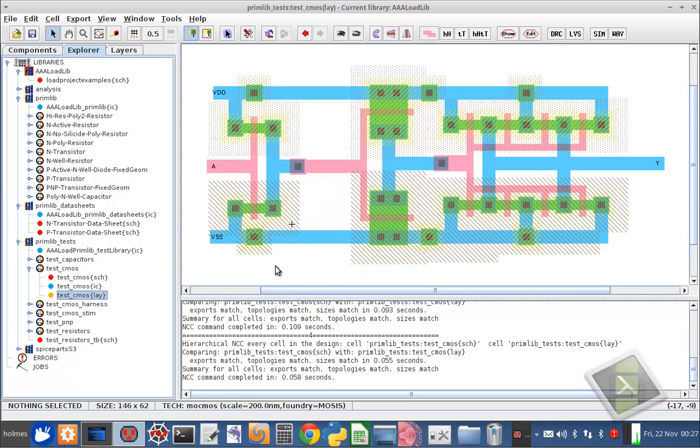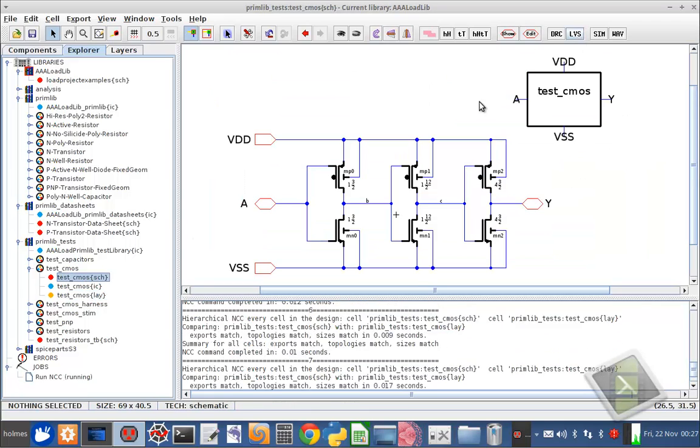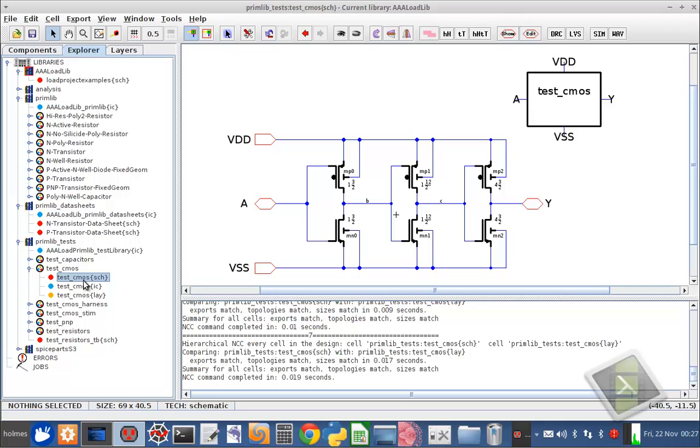The layout view is the drafted representation of the schematic. You can run LVS from either the schematic or the layout. It doesn't matter. It will equivalence the two by name. So if a schematic and a layout have the same name and they're organized in the cell this way by name, whenever you run LVS, it will compare those two together. There are ways to compare a schematic of one name to another, but in general that's not recommended. It's better to keep the nomenclature and your naming of the cells equivalent. That way all the LVS is done very easily.